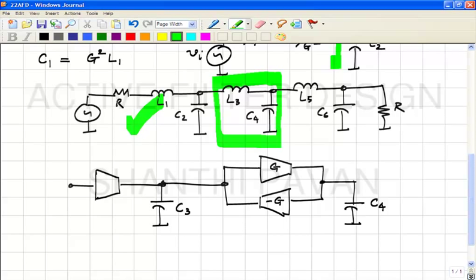In a series network, it is square root L by C divided by R. So in this case, it's a series network. The desired series resistance is 0. In other words, you want both poles to be on the imaginary axis. The quality factor is infinity, which means that the LC network need not be damped, so you don't need the damping transconductor. Is that clear?